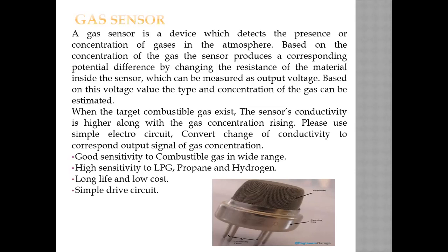So therefore, it should have good sensitivity to combustible gas in a wide range, high sensitivity to LPG, propane and hydrogen, and long life and low cost have been very important. A simple drive circuit has been employed for these gas sensors. So like that, the gas sensors have been used so that the intensity of combustible gas and its conductivity can be found out, so that we are able to estimate what will happen, to make the environment safer and safer, not to have any sort of